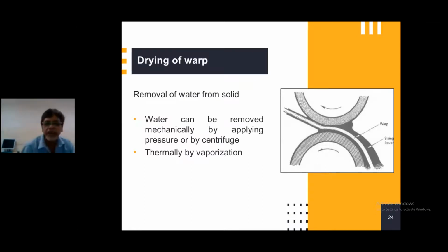by thermal vaporization. We all know that if you want to use thermal means, then the cost of energy will be much higher. So that's why in this machine also we try to remove as much water as possible mechanically, and then apply thermal drying on it.